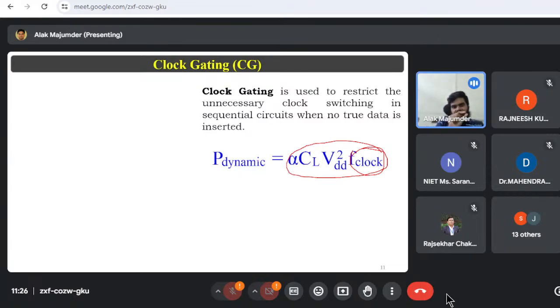So at the very initiation of the operation, they are not directly hitting the 2 gigahertz. They are giving a continuously changing frequency, and the frequency will get locked at the peak frequency at which you should work, which is 2 gigahertz, for example. So a PLL cannot do it. A PLL will only generate the frequency you need. So for that, you need to design some circuit which will actually do this generation of a variable frequency clock, right?